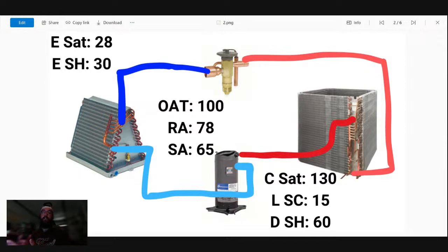If it's not, and you see that it equalizes to a significantly different saturation, then yes, that could either be non-condensables, which usually you're going to see a higher saturation, or it could just be a wrong refrigerant altogether. That would be one way, or maybe somebody mixed refrigerants they shouldn't have mixed. That does happen, especially with the drop-in stuff. There are quite a few people that believe drop-in means literally put on top of, and you can have a scenario like that. That's a good point. That's not something we typically think about, Joey. I sure don't.